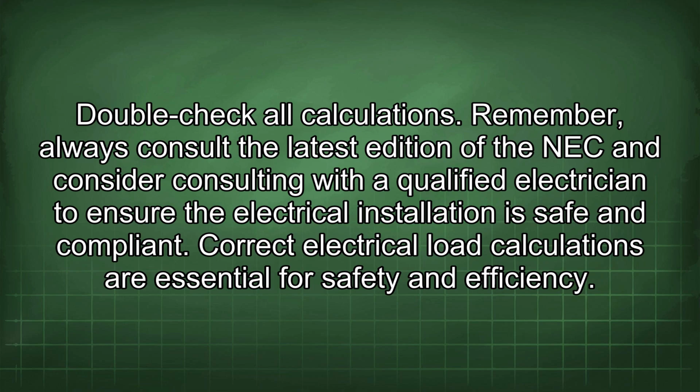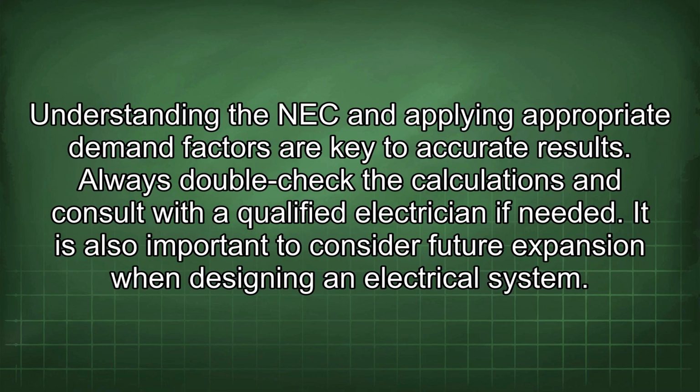Correct electrical load calculations are essential for safety and efficiency. Understanding the NEC and applying appropriate demand factors are key to accurate results. Always double-check the calculations and consult with a qualified electrician if needed. It is also important to consider future expansion when designing an electrical system.